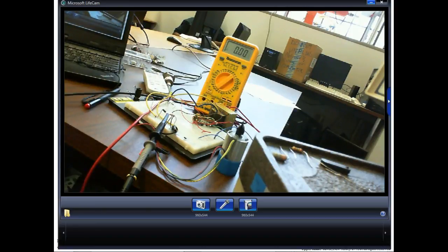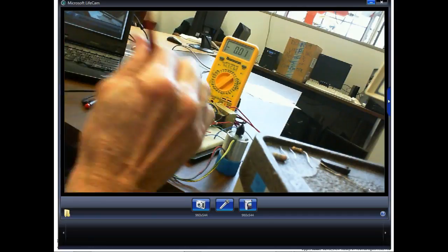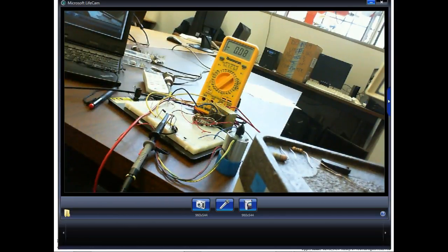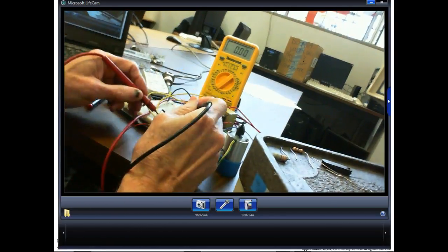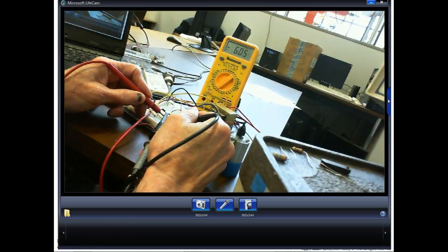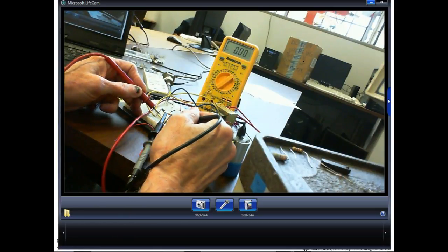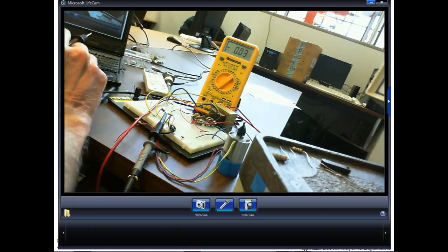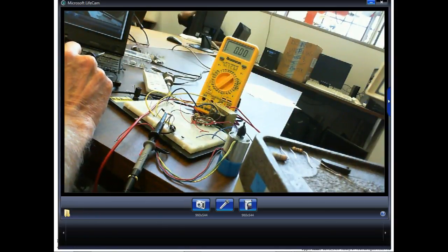Y'all understand that? And that gets people, they'll be in here probing, and this just gets me too. They'll come over here and measure, they'll record a minus 6 point something volts there, and they'll put 0 volts right there, and they don't realize you can't have minus 6 volts over here and no voltage from your source, right?